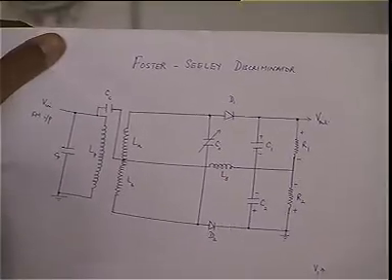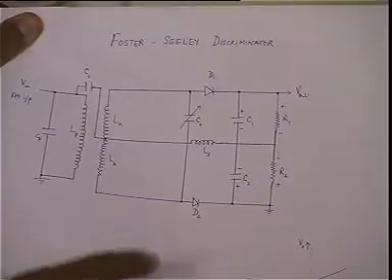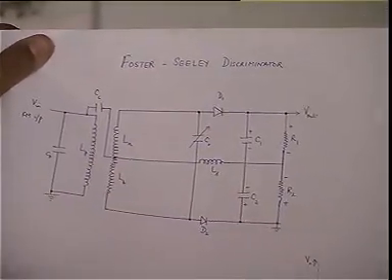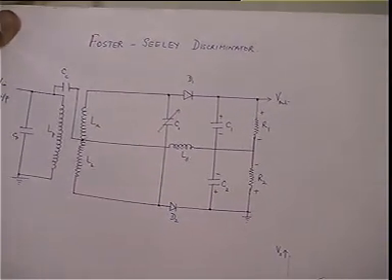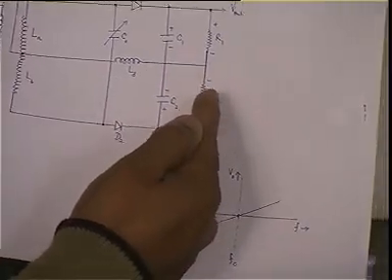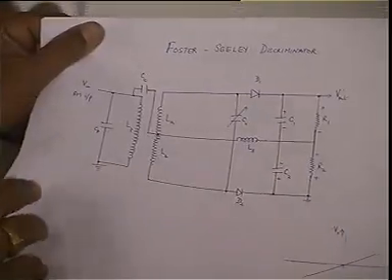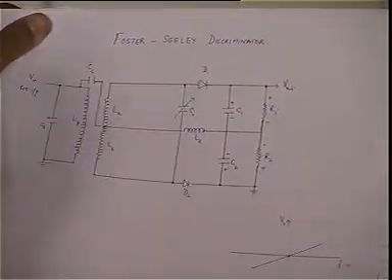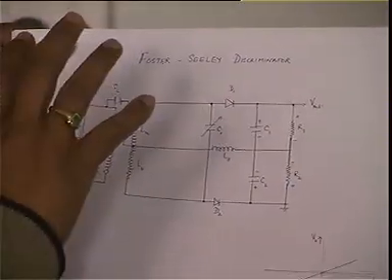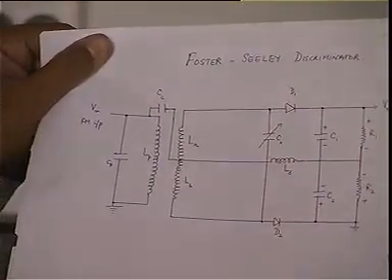Now, if the instantaneous frequency is greater than the carrier frequency or less than the carrier frequency, one of these two voltages will be larger than the other voltage. So what am I doing here? Depending on whether I am here or on this side, I will have this voltage more than this voltage or this voltage more than this voltage, and therefore at my output voltage I will be in a position to recover the message signal. So that's how I do a frequency to voltage mapping. The changes in carrier frequency have been mapped to the changes in the voltage. By doing that, I would have recovered the message signal.